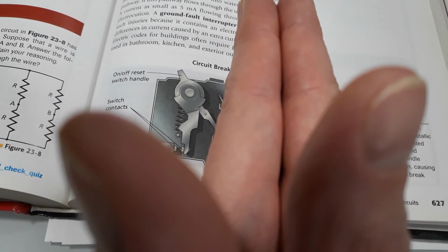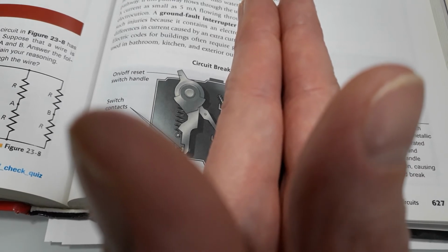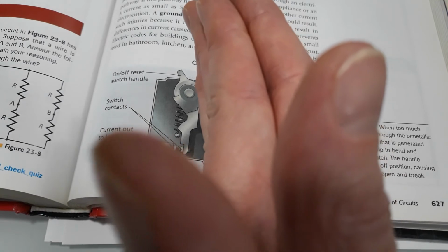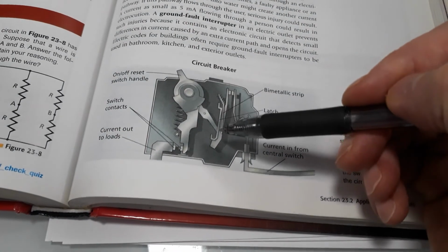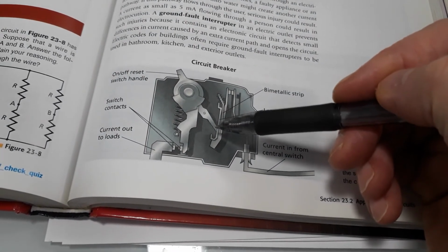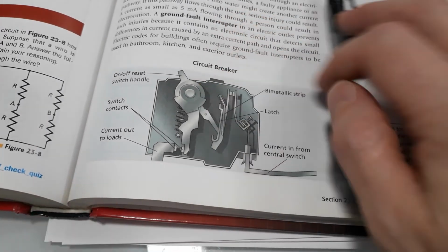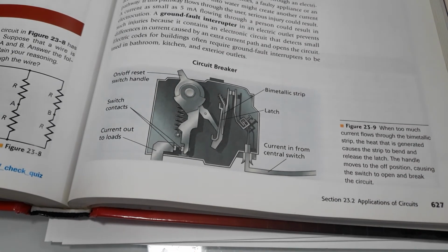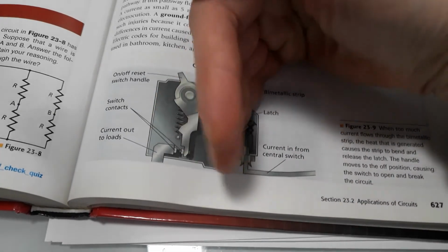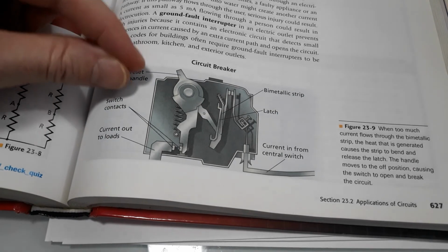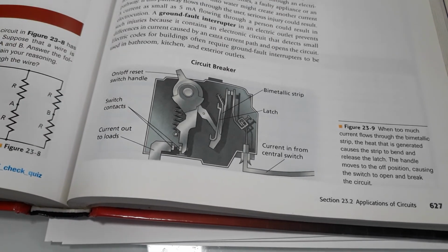And as it allows the electricity to pass through, it will heat up. It will begin to expand, but asymmetrically, so that it will begin to curve. And I swear to you, it curves until it pushes this switch. This piece right here will bend towards the switch until it shuts it off. It literally reaches and pushes and shuts the thing off. And of course, as soon as the current stops, it relaxes. So instead of pushing, it relaxes back to its original position. All you need to do is take the switch, reset it, and pull it back, and it will come right back on, and everything will work just as good as it did before.